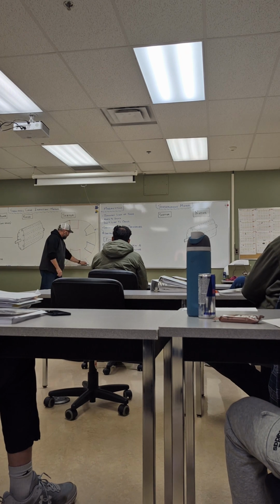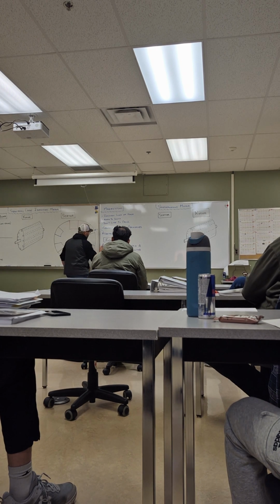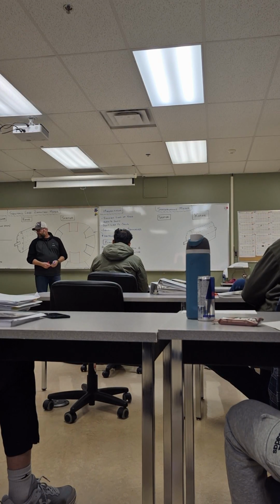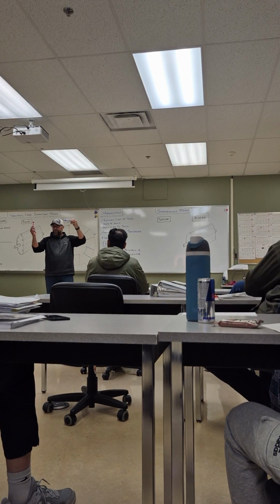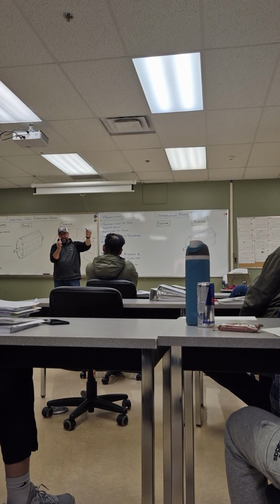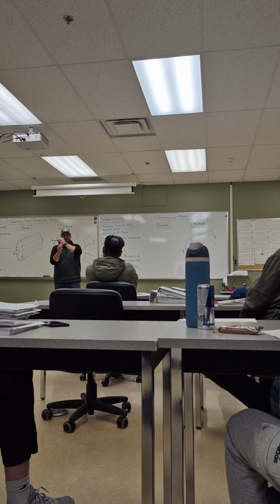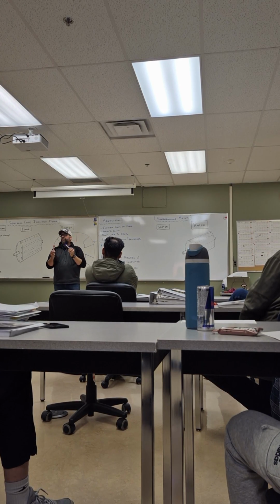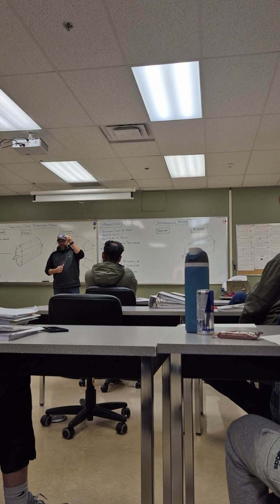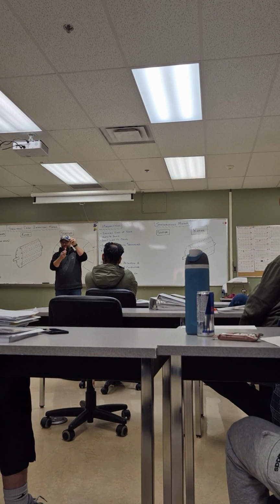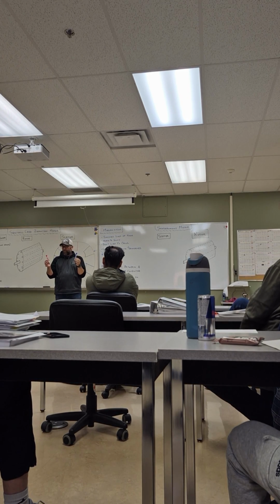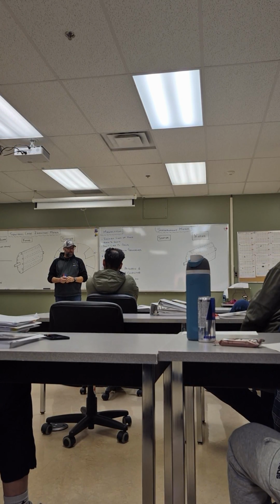Now you do have to really pay attention to this statement right here, relative motion. I'll show you what that looks like. Let's pretend that this is a conductor and this is a magnet. I can put a magnet here like this, and I can take this conductor, and when I go like this, past that magnet, this conductor will have voltage in it. That's no different in any way, shape, or form than holding the conductor stationary and taking the magnetic field and moving it. The relative motion, you don't care how you get it. There needs to be a speed difference between those two things for voltage to be induced.